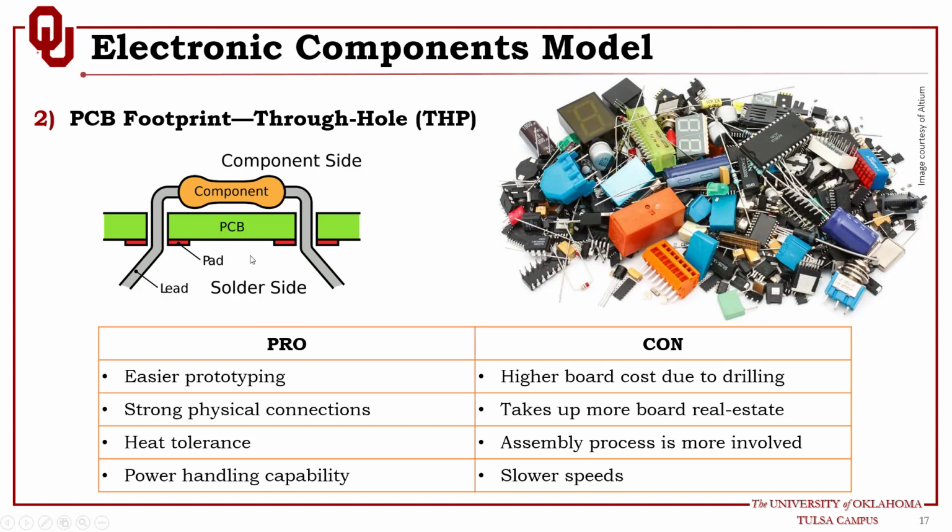So in this case, the practice for this through-hole component is to insert the component from one side of the PCB and solder the component from the other side of the PCB, then you cut off these extra leads. The soldering is done either by manual soldering, or they sometimes use something called a soldering wave machine. Try to Google soldering wave machine, and it's very impressive how they do the soldering, where you have waves of solder and the board will go over these waves, and these leads will touch the solder wave and will pick up the solder at these soldering joints.